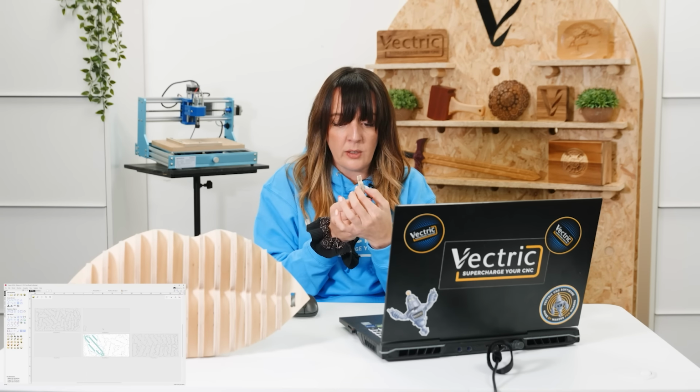Now when you are working with a slot together project, the idea is that you're going to be slotting one part into another, and we are using the material thickness of our tabs for our slots. If we don't overcut this, it's going to be extremely hard for us to put those tabs into those slot holes. We want to make sure it's tight, but not so tight that we're really struggling. So we need to check some of those parameters.